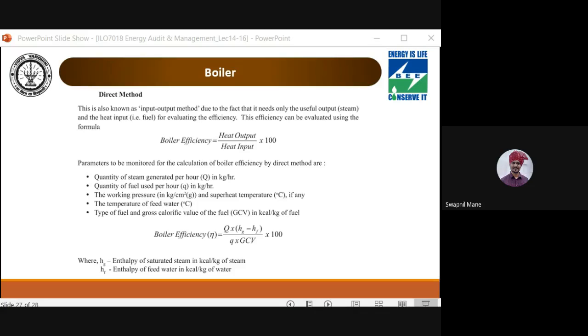So these fans are placed near the boiler exhaust, because the chimney will cause a pressure drop. There will be a pressure drop in the chimney, so in order to make these flue gases pass through the chimney, there will be fans. So the role of the fan is, yes, not just for fly ash, but this fan takes the hot flue gases and sends them into the chimney. The movement of these exhaust gases into the chimney, so that the chimney will dissipate these hot gases into the atmosphere, is the role of the fan.